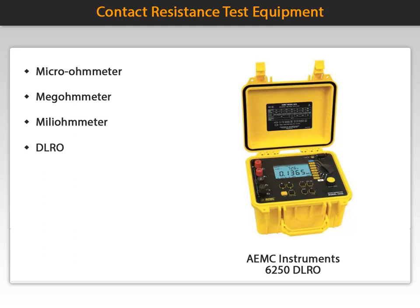This tester consists of a DC ammeter and a few other components. The test measures the resistance at the micro or milliohm level. All use a 4-lead Kelvin method of testing. We'll explain the Kelvin method in an upcoming visual. Some of these types of meters are also available in handheld type. For demonstration purposes, we will focus on using the DLRO to accomplish this test.